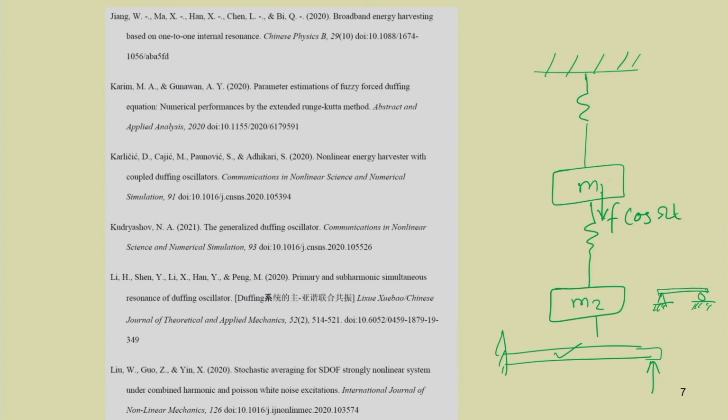In this case, you know the formula, and this can be modeled as an Euler-Bernoulli beam, where omega n can be written as beta square L square root over E I by rho L fourth, where beta L equals n pi for the simply supported beam. For n equal to 1, beta L equals pi, so the first natural frequency becomes pi square root over E I by rho L fourth.